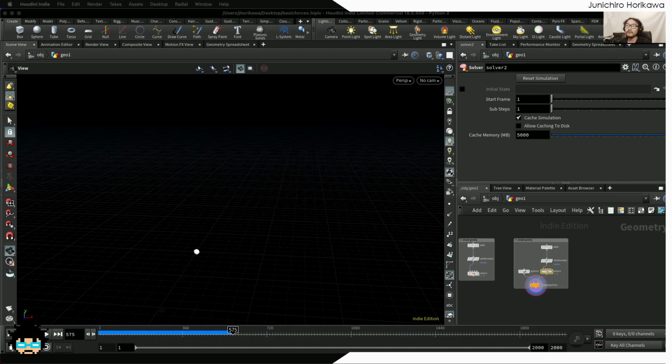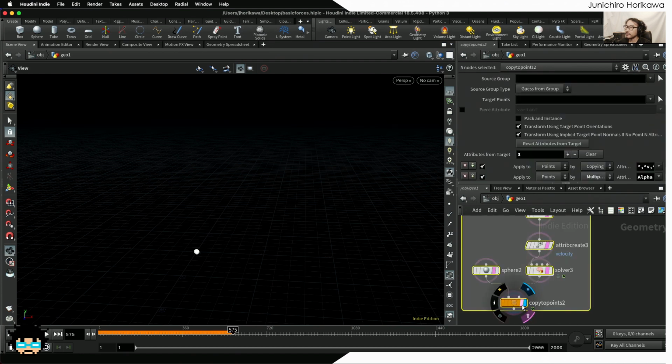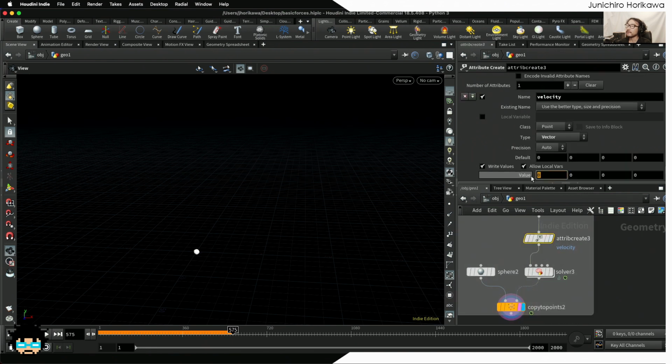Now sometimes when you do the force simulations, the object which you want to move might not start from 0 speed, but it might have some initial speed being applied. Initial velocity has already been applied. So let's try to see how we can do this in Houdini. And actually it's pretty easy to do. I'm just going to copy this one. And what you just need to do is go back to the initial velocity attribute and just set this initial value, and that's pretty much it.